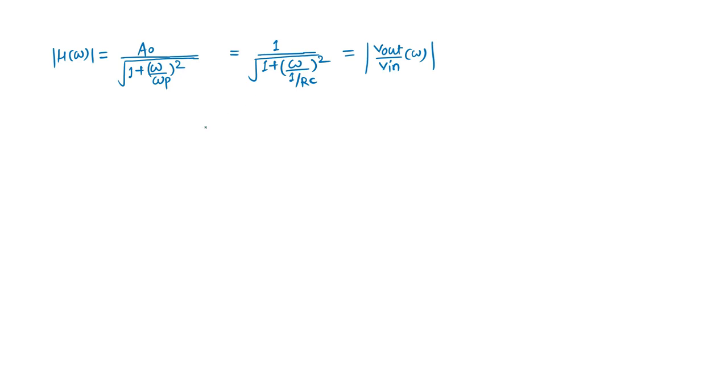Okay, so can you plot this magnitude with respect to the frequency? If I make a column, this is omega and this is the magnitude of H of omega. I'll see a few instants only. Let's say omega is 0, then it is 1. If I put omega as 1 upon RC, this is 1 upon root 2. If I put omega as infinity or much higher, then it is 0. A simple thing.